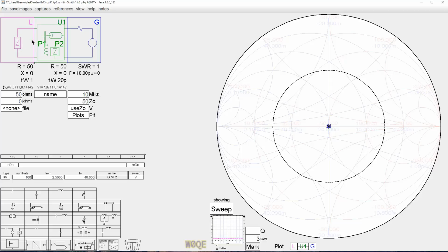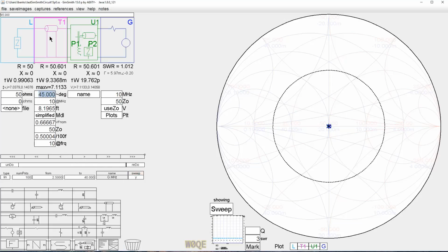To date, I have always done this by taking a piece of transmission line, and this is an artificial piece of transmission line. I make it lossless so that we don't get any spiraling on our rotation. And pretty much I set, let's say this is a 3 to 1 circle right now here shown. This 3 to 1 right here is this dotted line. Let's say I could start off here with a 3 to 1 impedance. It doesn't matter what impedance it is. And let's turn that off for a minute. I'm right here. And I get a rotation due to my piece of transmission line.